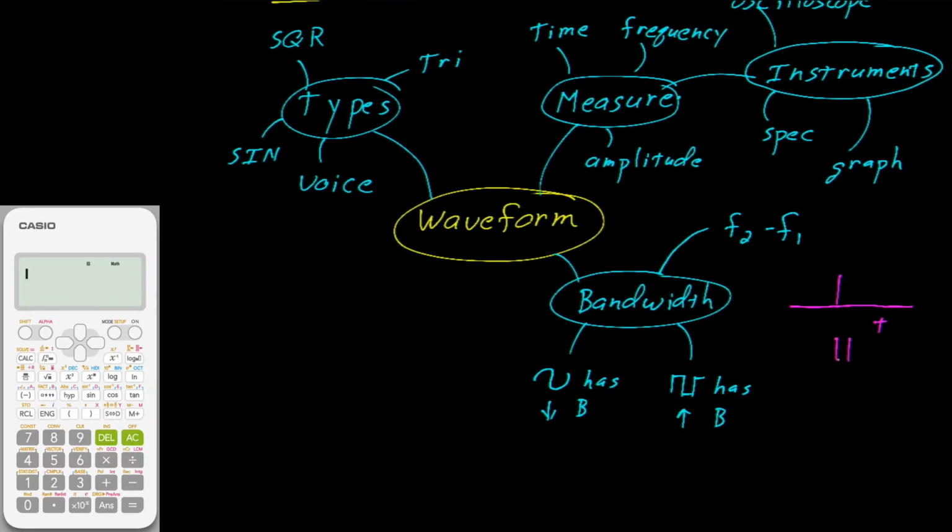That bolt of lightning, which appears so simple in the time domain, ends up in the frequency domain as having a nearly infinite frequency. So a spike in the time domain is all frequencies in the frequency domain. And I think that one's rather interesting. Anyway, the point I wanted to make is that these rising edges are problematic.